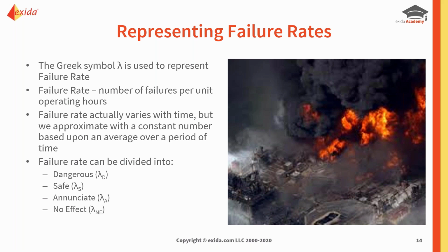If you're doing it the hard way using Excel, then you have to make sure that you get those failure rates to be able to plug into your formulas. So we all know, or most of us know, that failure rates are represented by the Greek symbol lambda, lowercase lambda. And failure rate basically is the number of failures per unit operating hours. Simple enough. And of course, we know that failure rate will vary with time. And we approximate with a constant number based upon an average over a period of time. So this we will get to in a couple of slides when I talk about this in a little more detail.